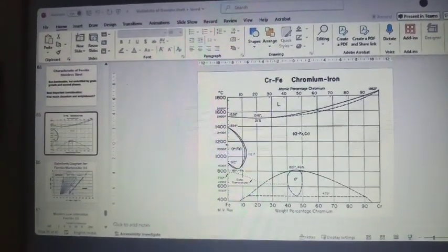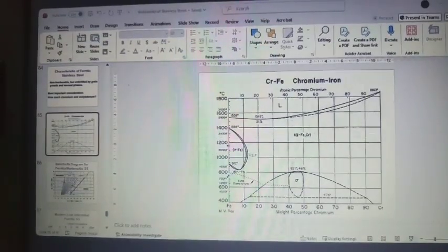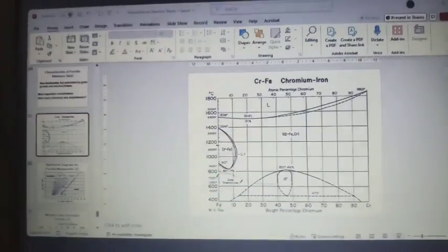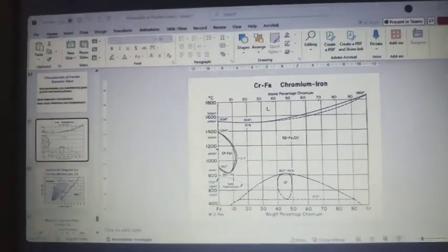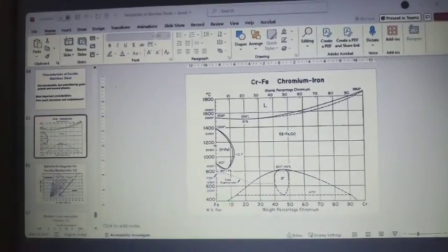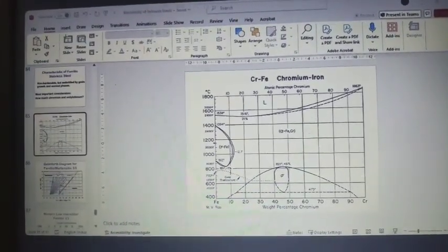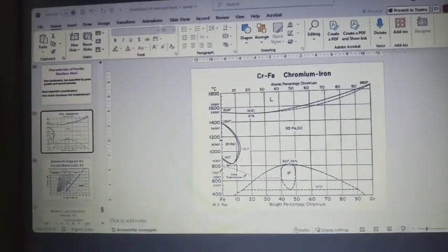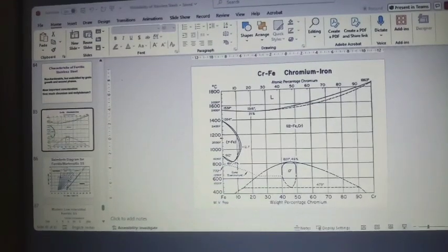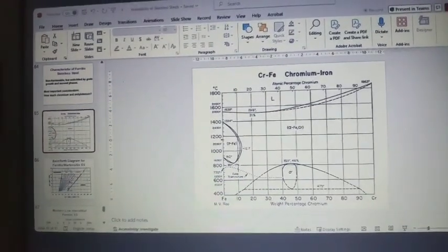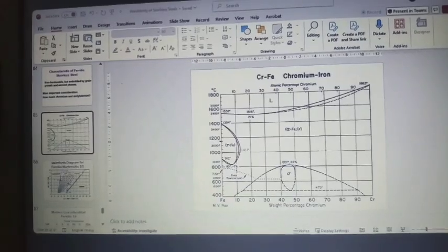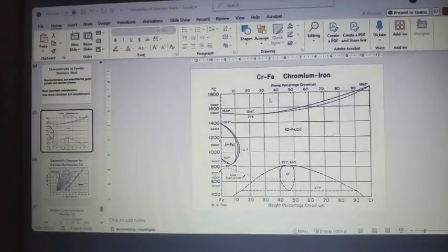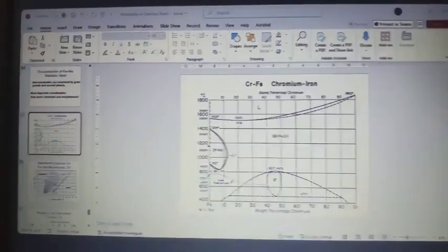Only where you want a moderate corrosion resistance but high strength and high temperature, because of your chromium you have some corrosion resistance, which is not very good, but some. So in this requirement, we generally go for martensitic stainless steel. That's why martensitic stainless steel is usually used in high temperature applications, or basically for pump impellers like that.